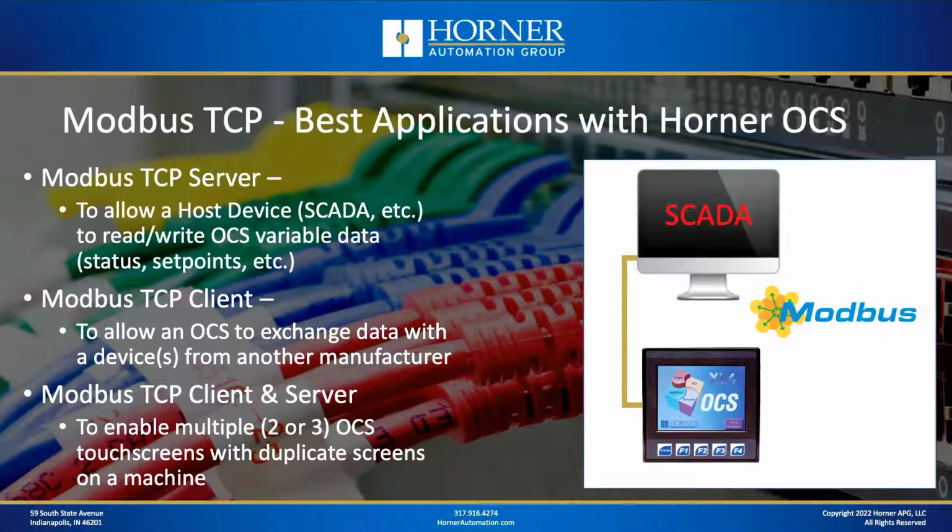All right, now let's talk about a great scenario for Modbus TCP as a client with our products. Again, in that scenario, the OCS is polling other devices that are servers. Here's an example. You've got a variety of third-party devices, maybe variable frequency drives, and you want to be able to control those drives and get diagnostic information and do fault resetting and all those sorts of things over a network. Well, Modbus TCP client executed in the OCS is a great way of doing that.